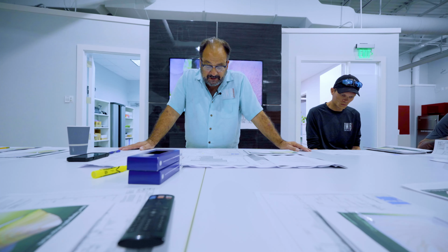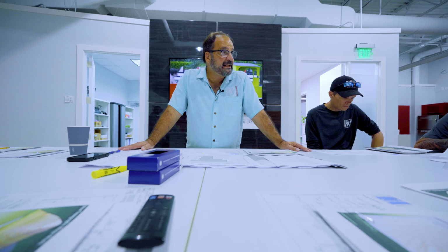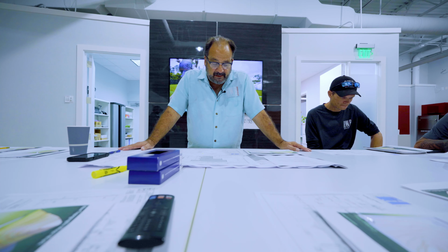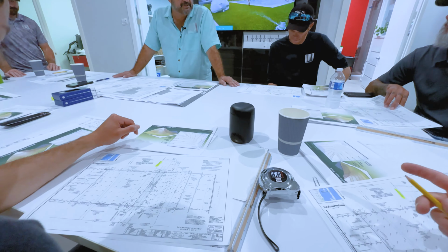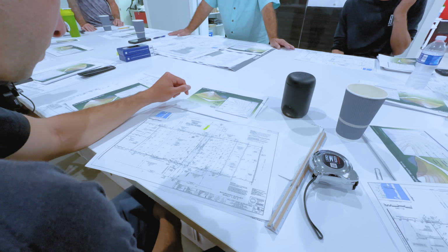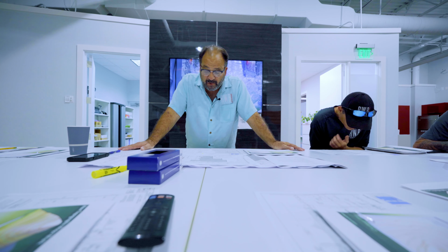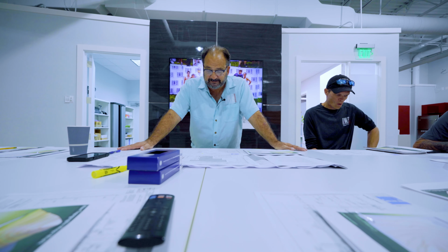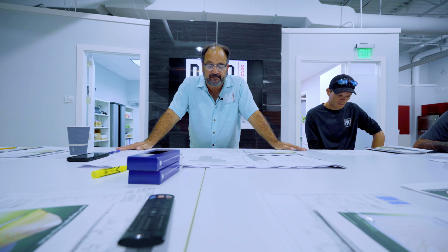Okay? When you start a project, a surveyor comes out and he basically surveys the entire plan and does a drawing to scale that everybody works off of. The topo part of it is actually pinpointing certain grades on the property and on the adjacent property, as well as elements that exist, such as trees, site walls, fences, things like that. All these are going to aid him in determining what has to be done going forward.